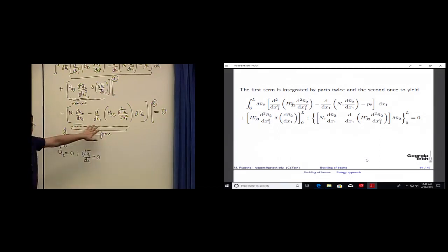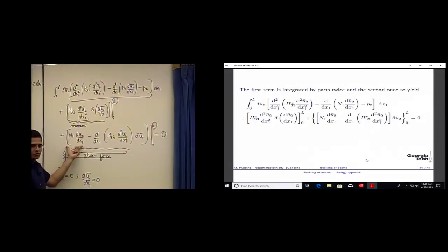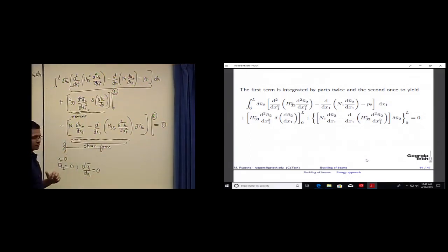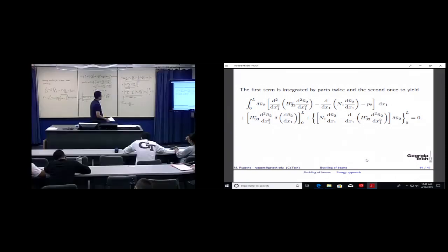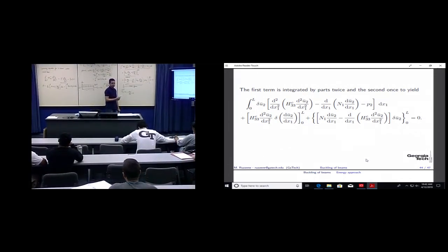It was the resultant shear force. We saw yesterday that the shear force boundary condition has another term due to the axial force. So using energy methods, we can get the shear force boundary condition and the moment boundary condition if it's a cantilever beam. But if this beam was a simply supported beam, we would get the moment boundary conditions and the displacement boundary conditions accordingly, right?